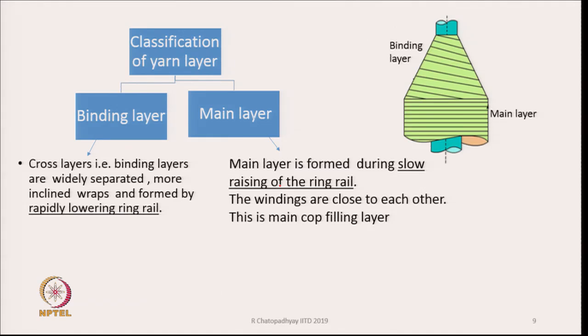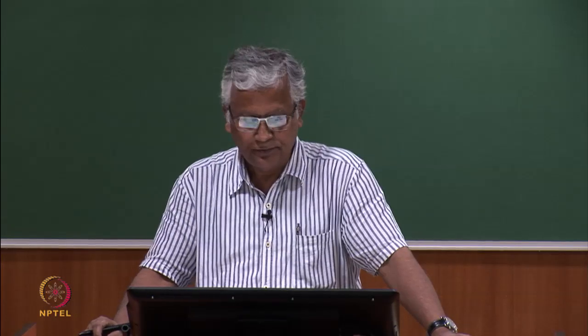We do not lay the yarn in the form of roving wheel. We are laying the yarn in short strokes over a shorter length, and when that length gets filled up, we go to the next position. So, in short strokes we keep on laying the yarn. We do this because we need to have less tension variation when we are actually unwinding the yarn at high speed.